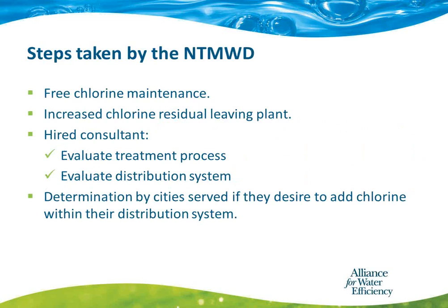So what are the steps that the district has been taking? Again, we do the annual free chlorine maintenance. We have increased the chlorine residual leaving our water treatment plant. We have to be very mindful of the cities that are closer in. Right now we have around a 4 milligram per liter leaving the plant. And so we've increased as safely as we can the chlorine residual to not have effects on the cities closer around us.